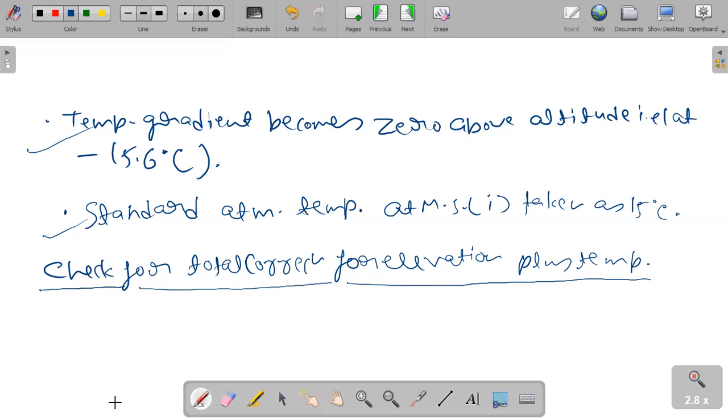Okay, look here also ICAO recommends that if combined correction exceeds 35% of basic runway length, then these corrections should be further checked and specific studies done at the site by model testing.